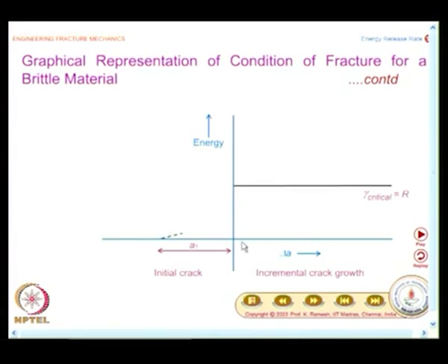You have to look at how these axes are labeled. On the positive x axis you have incremental crack growth. On the negative x axis you have the initial crack. This is something different. This kind of graph you would not have used in other disciplines. When you come to fracture, different types of graphs are presented. On the y axis, energy is plotted.